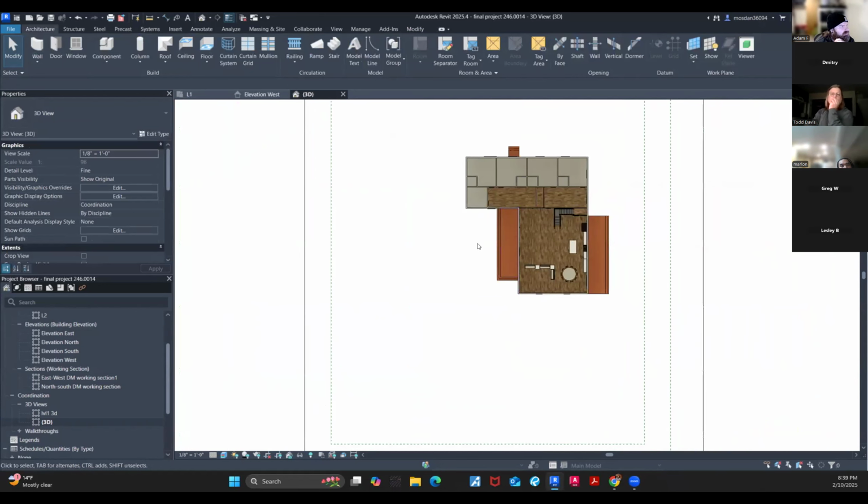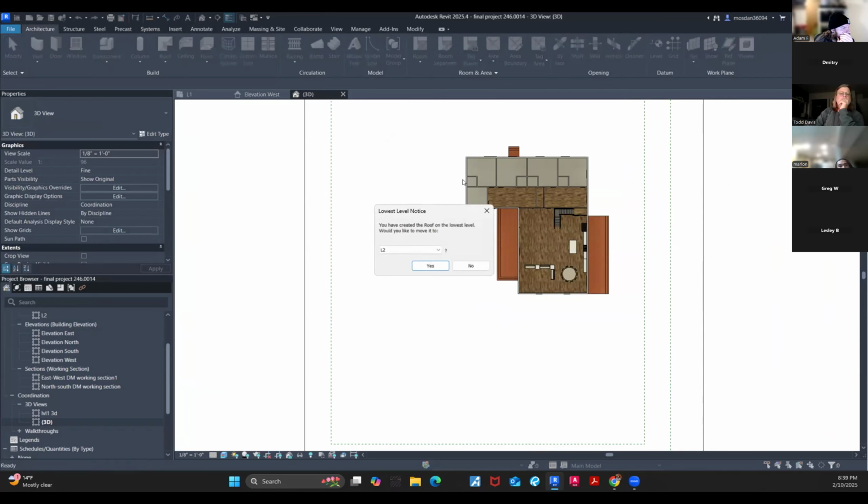So before we get anywhere else, I want you to do what I did in that roof by extrusion example, where we create a reference plane. In this instance it doesn't matter where we create the plane as long as it's a true 90, because we're going to create a flat roof in this one. The next one will matter, and we'll make it sloped, but we're going to create a flat one to start.